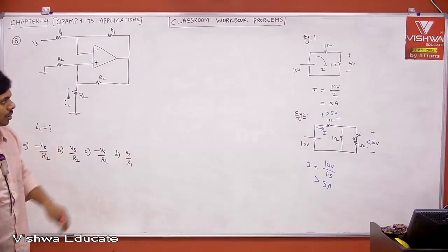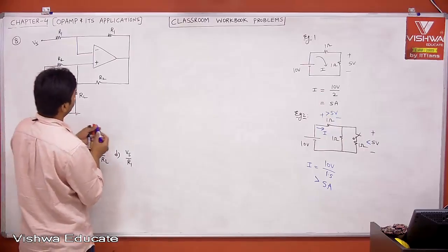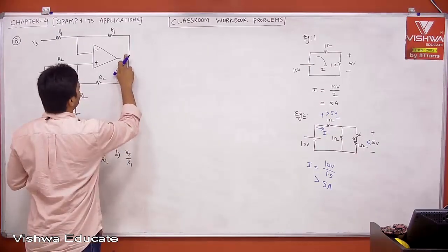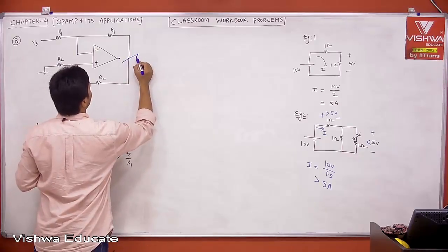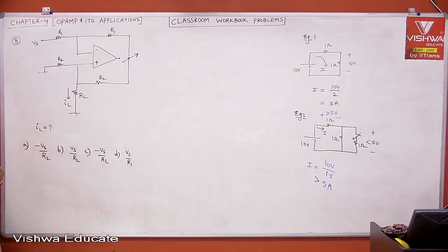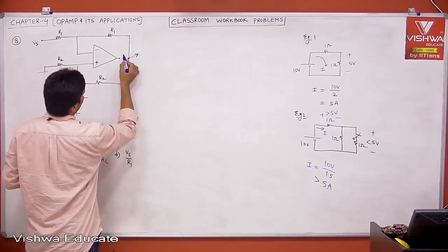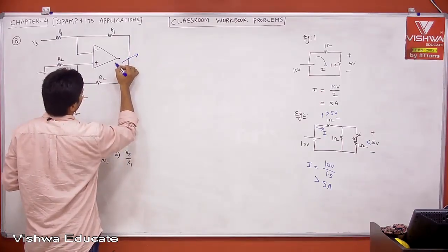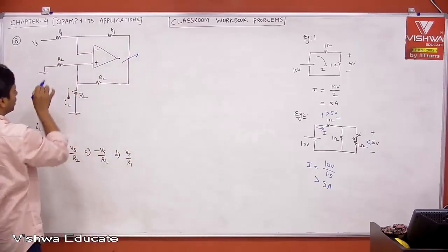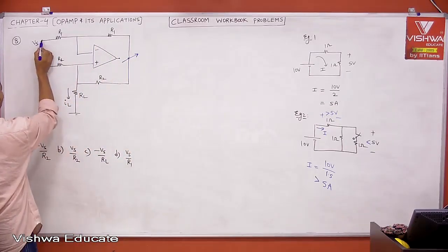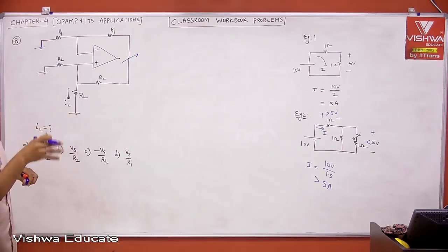Just listen. I'll give you time to write down. Now, let me apply it. What is the technique? Open the loop. Now, let us increase this voltage. When you increase this voltage, I want to know what the change is here, whether it is increasing or decreasing, only because of this and not because of anything else. If there are any other sources, make them inactive. Therefore, take them as ground only. Don't modify the original circuit; you have to draw it once again.